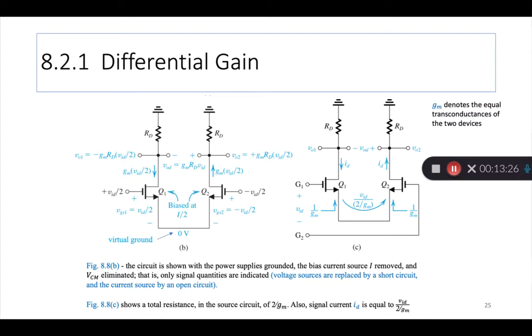Remember when we were studying Thevenin's theorem many years ago and we were creating a way to measure Thevenin's resistance from the output terminals? The rule we were told was you should short circuit DC voltage sources and open circuit current sources. So same logic here.